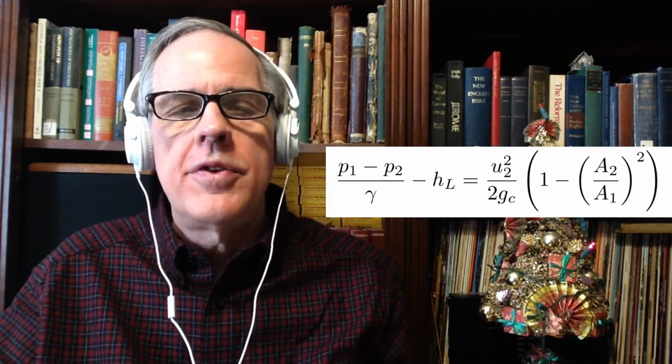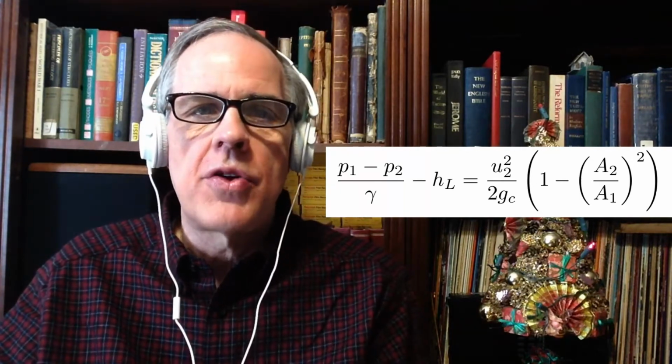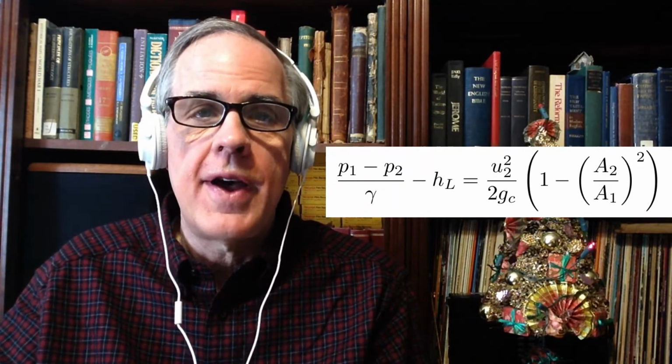The next assumption we're going to make is that the velocity is uniform across the cross-section of the pipe. That's not really accurate either, but particularly in turbulent flow, it's good enough for our purposes. So we make that assumption. We do some other math, and we end up with an expression of what we would anticipate the change of head across, in our case, a flow device would be.